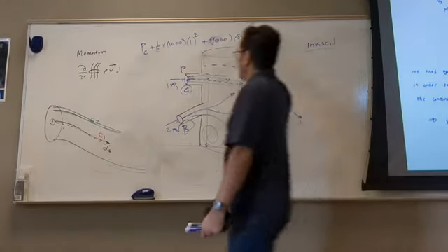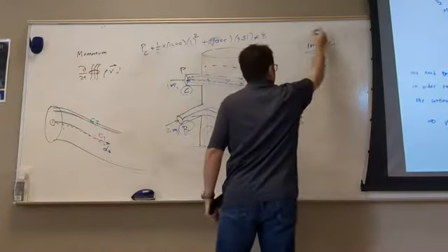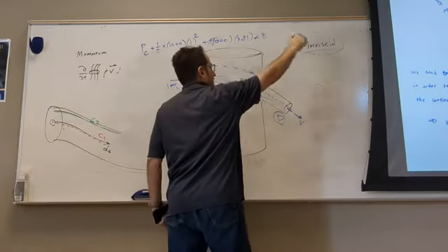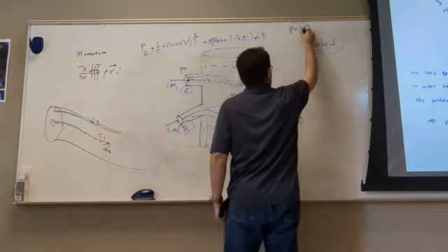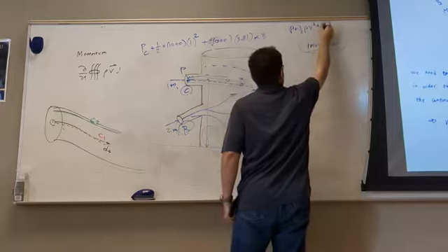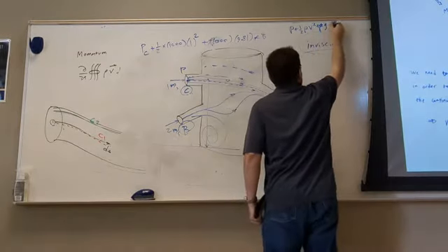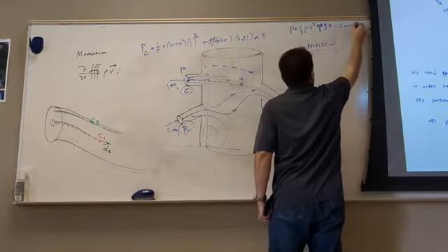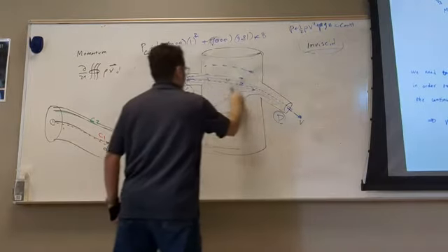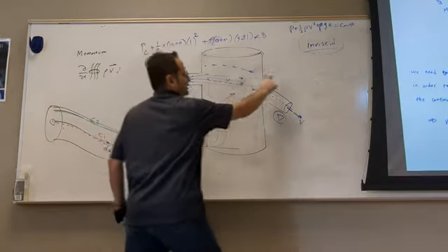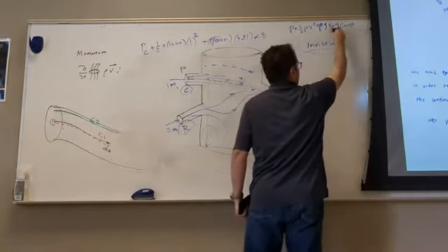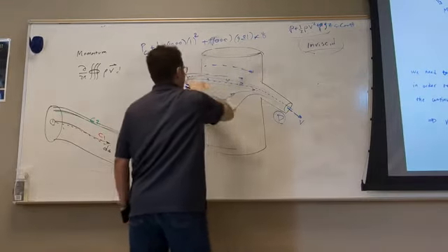Now, if you go to the derivation again, I go back to the first minute of class. You have the momentum equation, and the only assumption was inviscid. Then you get a sum, P plus 1/2 rho V squared plus rho g Z. This constant is only valid across one streamline. If you change the streamline, this will change. That means you cannot say this is equal between this point and the point here.